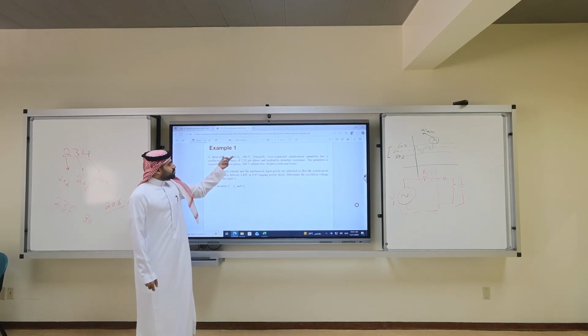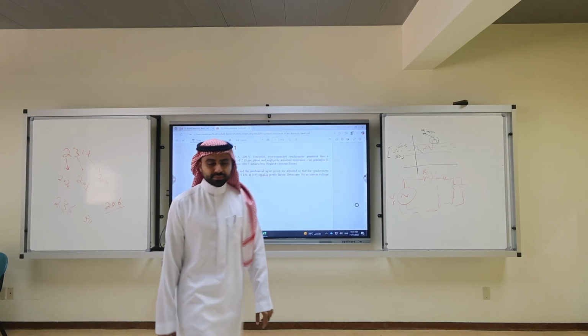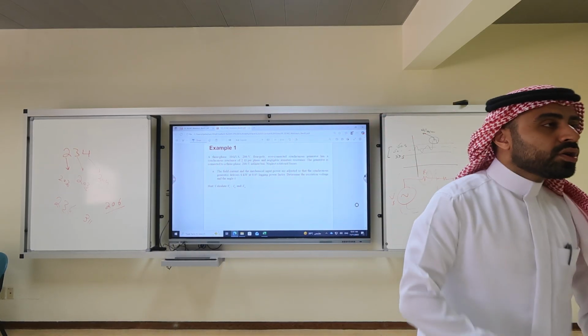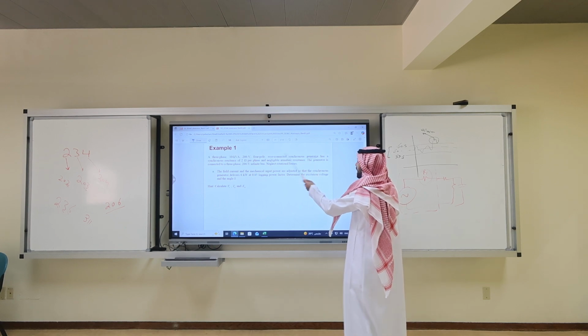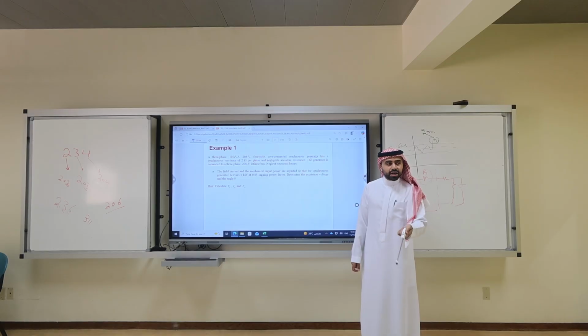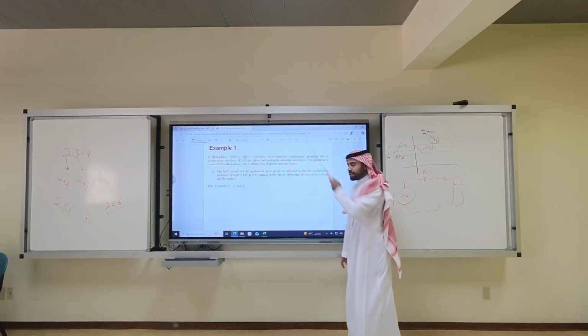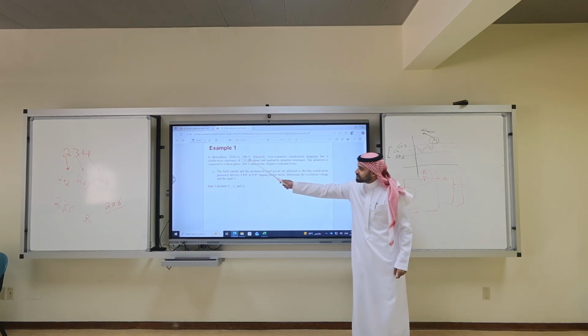Three phase, 10 kVA. Why isn't it 10 horsepower? Because this is a generator. How can I market a generator with a horsepower? Do you market a generator by the amount of power needed to operate it, or by the amount of power you get out from it? You get out from it. That's why it's 10 kVA.